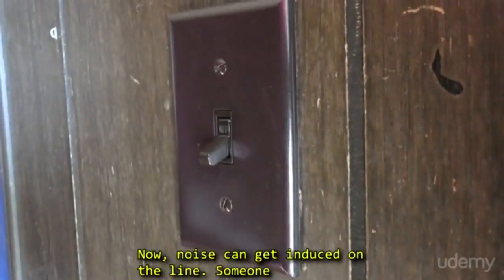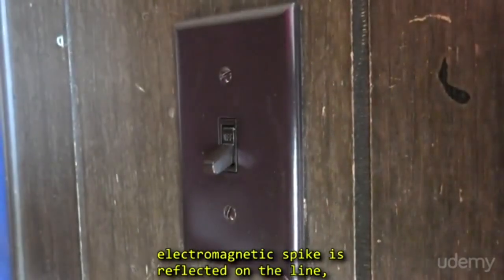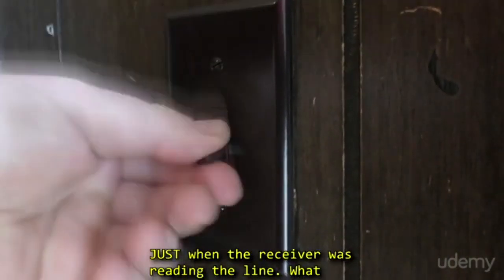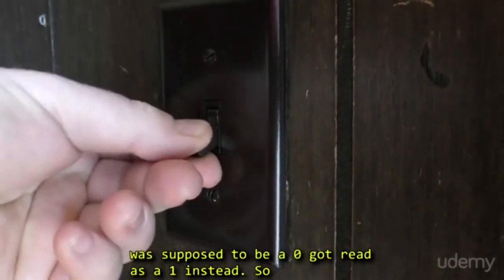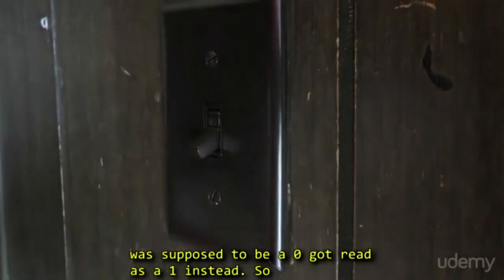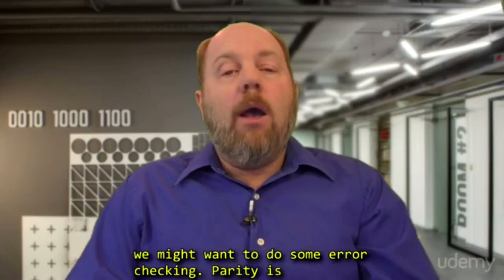Now, noise can get induced on the line. Someone turns on a nearby light switch, and an electromagnetic spike is reflected on the line just when the receiver was reading the line. So what was supposed to be a 0 got read as a 1 instead. So we might want to do some error checking.